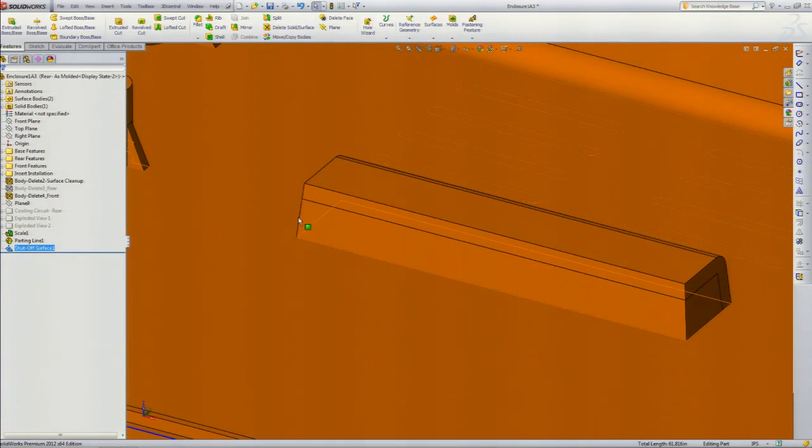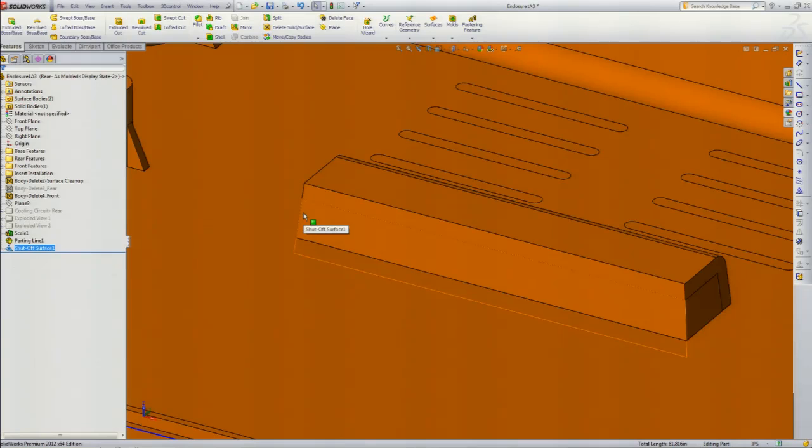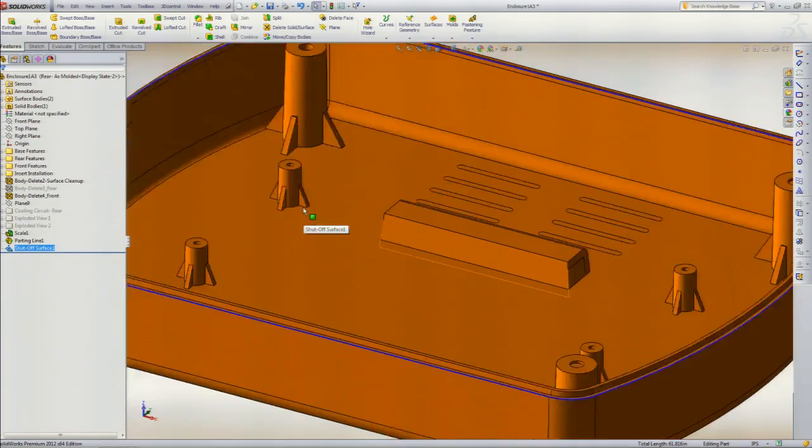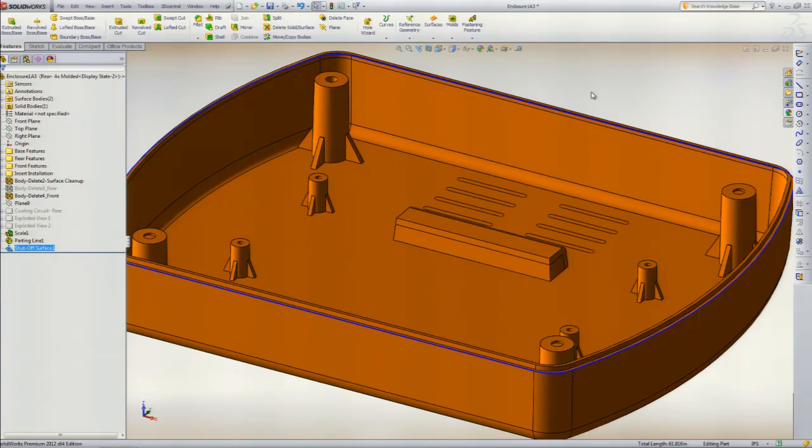And now that puckering is no longer there, and this is something that can be readily tooled up. Any questions on shutoffs? Why are there shut-off surfaces on the bottom? You've got shut-off surfaces on your mounting bar. Right, because that's 9 below. Yes, the software notices where the interface between the core and the cavity steel is. It will put a shutoff there to separate the two.